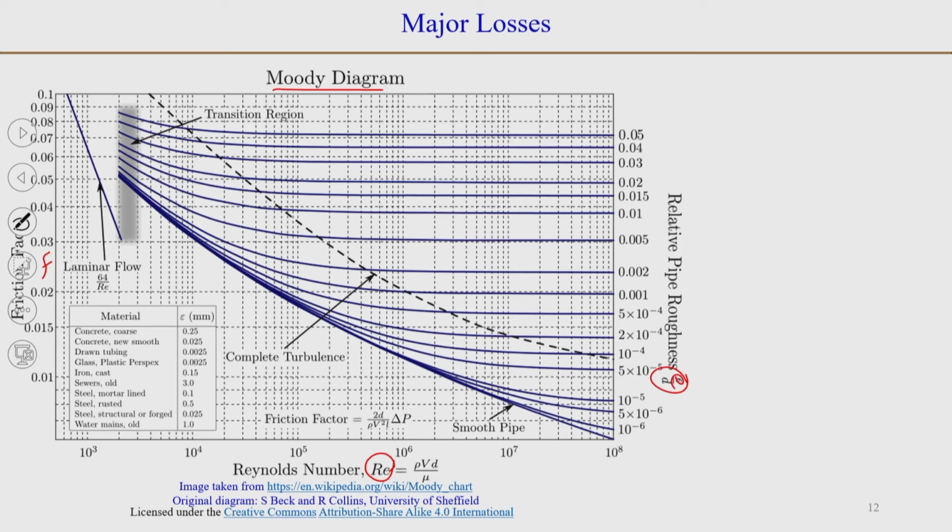Now, when the flow is laminar in this range, then you see a straight line, because the graph is a log plot, as you can see from the axis. The x axis is log and the y axis is also a log plot here. Okay. So, you see that this is a straight line, and for laminar flow you have 64 by Re, it is independent of roughness factor. Suddenly, as the Reynolds number increases, you see a sudden jump in the friction factor.